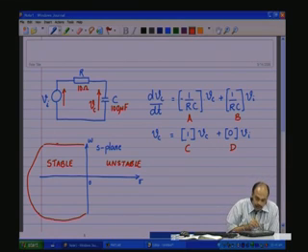One thing that you should note is that this is a system which has only one state variable, one differential equation, and therefore, there is only one root to the characteristic equation or one eigenvalue, and therefore, there will be only one pole, and that one pole will be on the real axis, because if you have a complex pole, then you have to have a mirror image also.